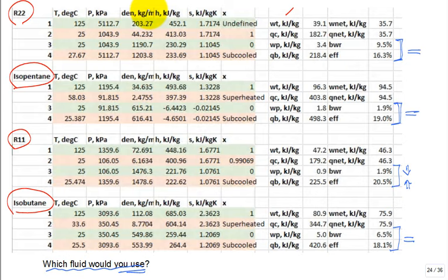Somebody says, well, I don't have a perfect turbine. My turbine is only 85% isentropic efficiency. And then you've got to run your numbers, right? And so there's some optimization. But you've got the picture. This is good, and this is good. Low backwork ratio, high thermal efficiency. And isn't it surprising how much it changes? I mean, why aren't they all consistent, Professor? That's a big difference between 2% and nearly 10%. It's the properties of the fluids. Okay? All right.